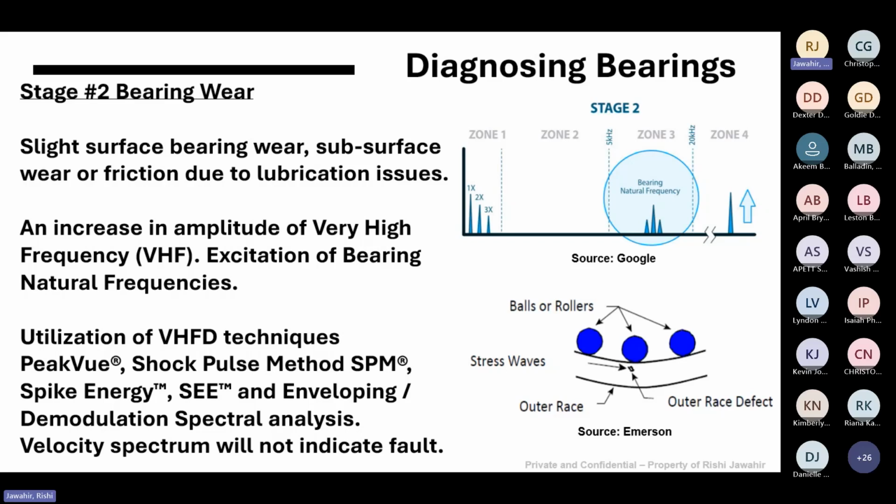So we still use these techniques, the very high frequency techniques. We still use them, we still employ them, which is peak view, the shock pulse. We still use these techniques, and you could also use something known as enveloping or demodulation. We will get to that shortly.